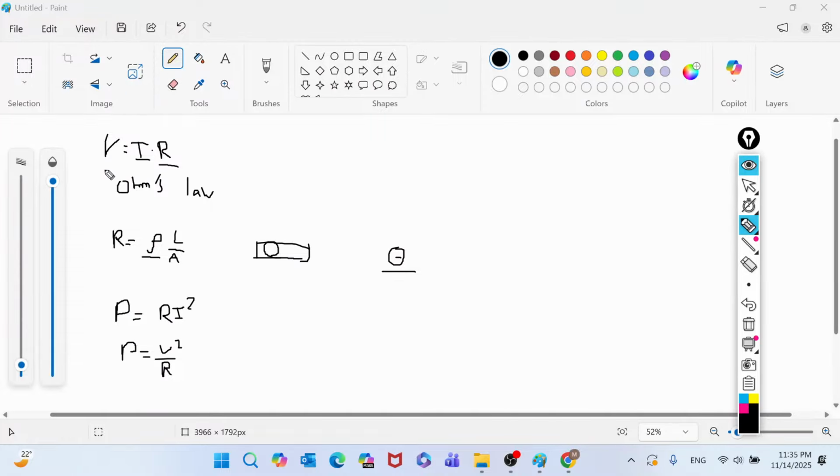and the resistance, just use Ohm's law, find the voltage, and you can use P equals I times V. Way easier than doing R i squared and V squared over R. Just find I and V and use this. If you have voltage and resistance, you can find I. If you have resistance and current, you multiply them, you get V.